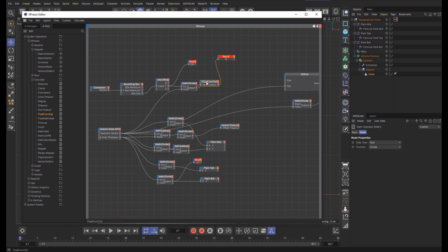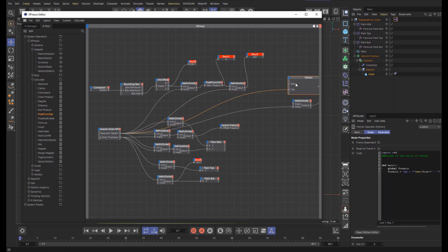And then what we just need to do is multiply 9 by the segment height to get a new height. So I'll just grab this here, change it to multiply, and we're going to multiply 9 times segment height, and that will give us this result, 207, which is what we need to have for the size.